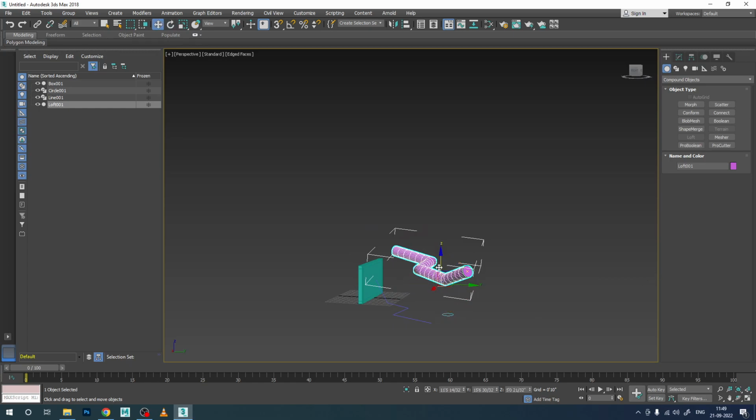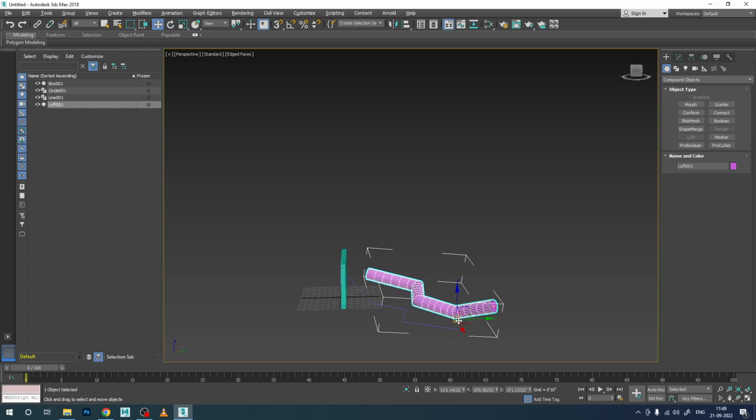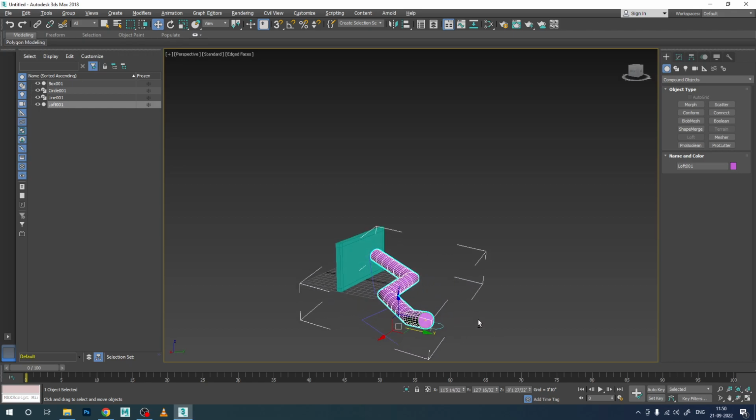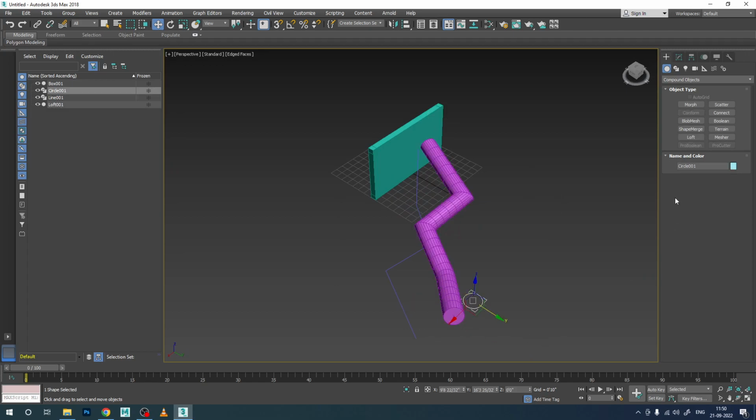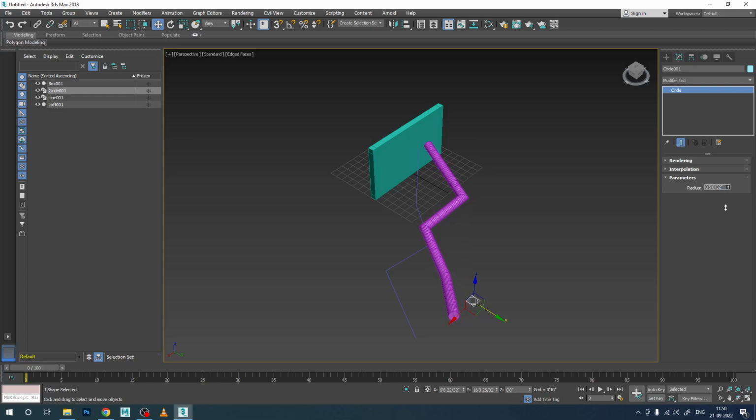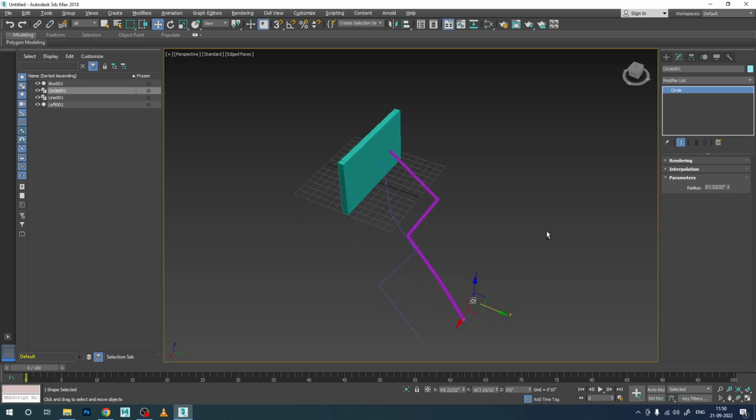Okay, now just move this one down a little bit. Try to properly align this one. And then we want to modify this circle. Now I don't want this much length, I mean width, for this one. So select this one, go to the properties, and define the radius value a little less. What happened is that the model is automatically getting changed as well.